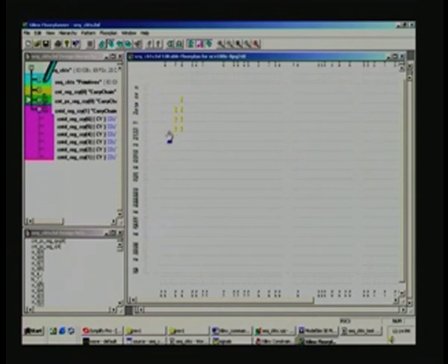And this would complete all the tools we have seen so far. ModelSim for simulation, followed by synthesis using the Simplify tool, followed by place and route using Xilinx, and also to back annotate. Finally, the back-annotated file we took into ModelSim, simulated once again and made sure that the whole thing is intact, and we have also seen how to change the pin constraints and clock constraints. This completes, in a sense, all the tools, and we will consider other applications shortly.